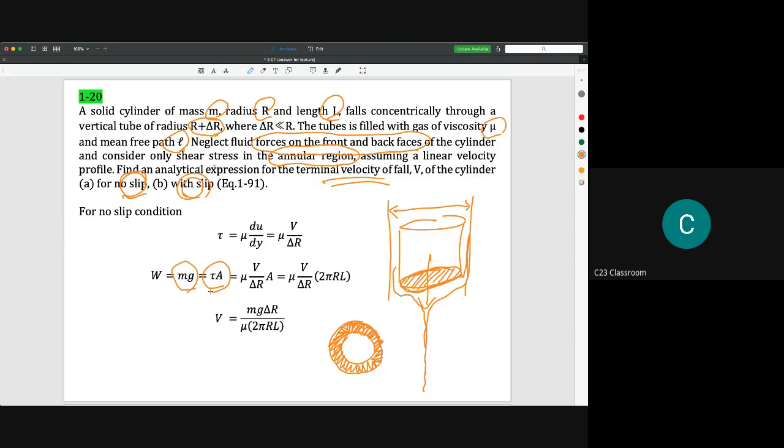The shear stress force actually occurs when the molecules stick on this area. This is quite easy because in this situation the axis is vertical. The force is equal to the shear stress times A. How do you make this assumption?